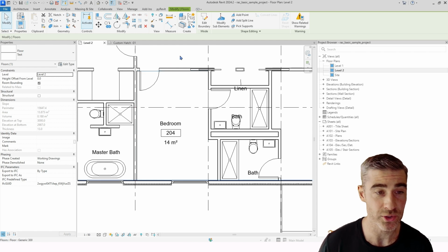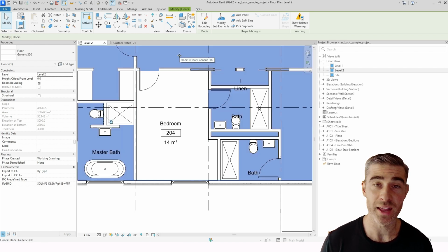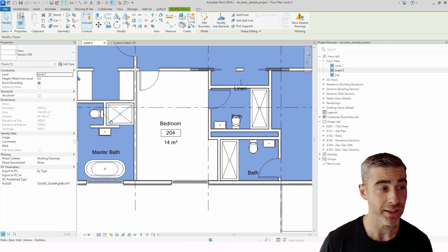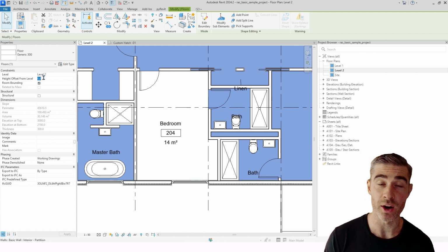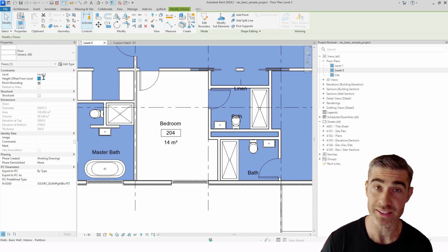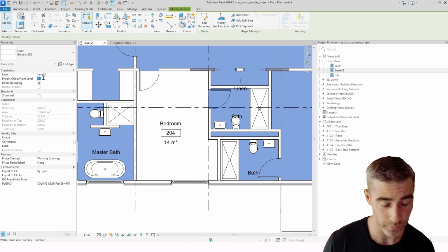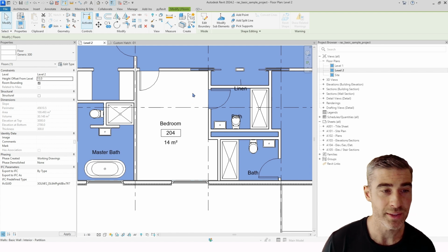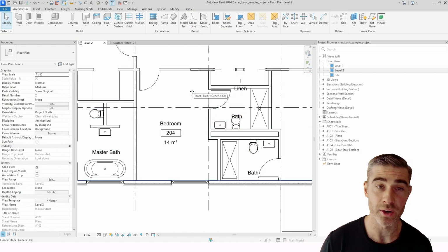So here, potentially, there is a floor created, and that could be from the linked model. That is the actual architectural floor, structural floor. So in that case, we want to potentially start to offset this. This is where sometimes a little math will come into play, depending on the thickness of that assembly. If we want to sit just perfectly on top, in this case we're going to change this to 13. Then this way, that does sit above our floor.